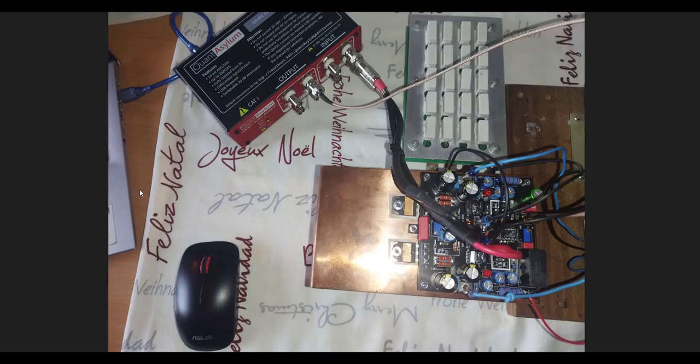Okay guys, that's all. I hope that you enjoyed this video. The idea is this one: increase the open loop gain to the maximum. You start to see some overshoot, some oscillation, and after this you can adjust this CX cap and try to win some additional phase margin. At this point you are in the limit of this amplifier, and the THD will be the maximum that this amplifier can produce.